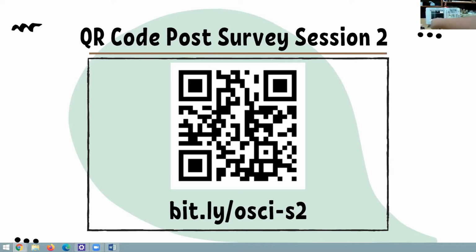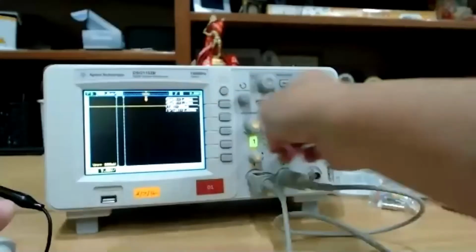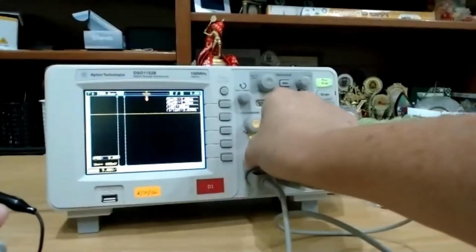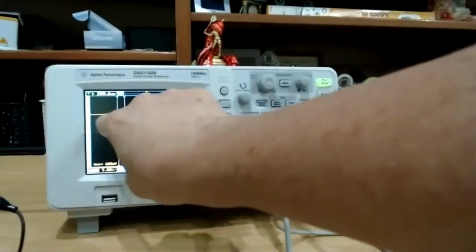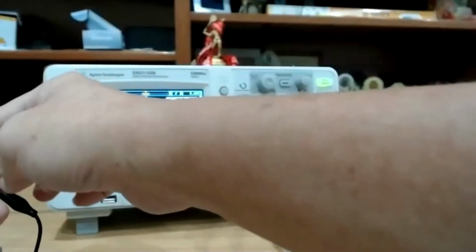So over here, channel 1 is 10 volts per box. You can see here 10 volts per box. I can change it to 5 volts. So if I put in the battery here, I measure. This voltage here actually went up. It went up and you can measure one box. From here, one box is 5 volts, 2 boxes is 10 volts. Actually, this is a 9 volt battery.